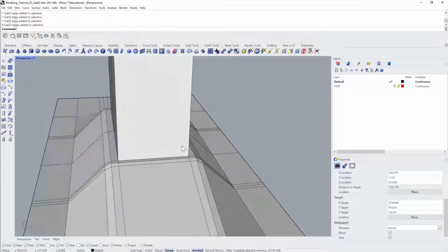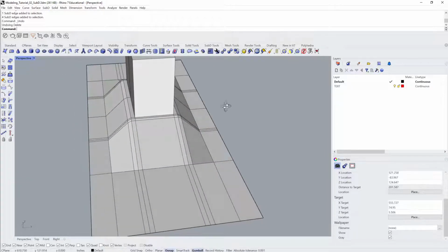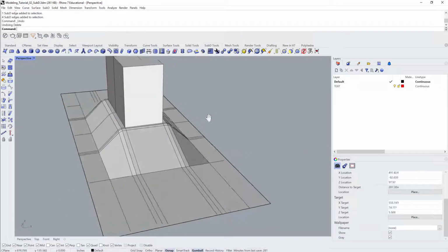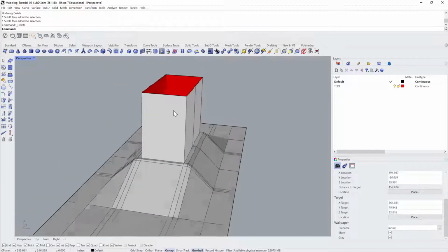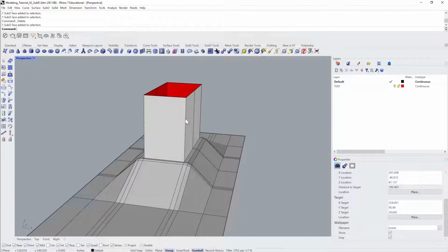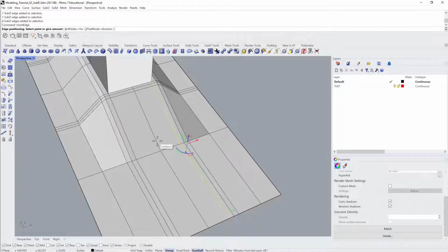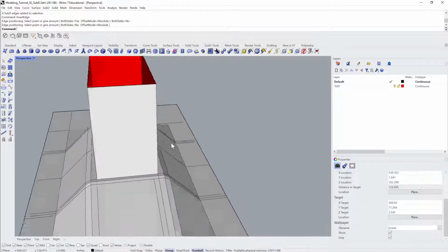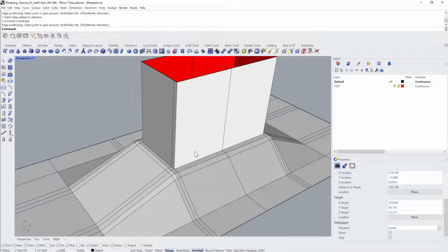Insert an edge loop that really cuts across this thing. You know, this is where planning a little bit can be helpful. What would be the best way to do this? Let's delete that. Okay, what happens if we insert an edge here? Both sides, no. Okay. So now if we insert an edge here and link it up to that one.